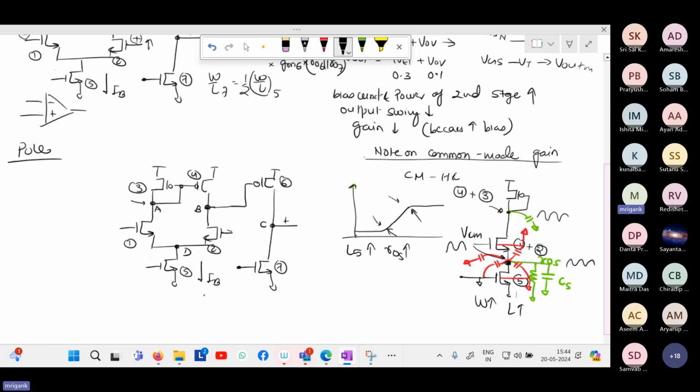And if you want to make it cascode, another option is to use a cascode current mirror. So rather than putting one, you put two of them like this. Then the impedance is GM RO squared, GM RO times RO. You know the impedance looking into the cascode mirror. What is the impedance? This, right? This is the small signal resistance of the cascode mirror. So if you don't remember it, try to derive it. I think you might have studied these things, right?